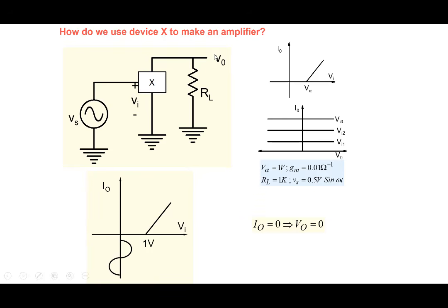So the issue before us is that we don't have an ideal transistor. We said an ideal transistor is not available. What you will have are elements with all kinds of non-idealities. So suppose we have a non-ideality like this here. Then if we simply connect an input to this kind of a non-ideal transistor, it's not going to amplify. Note that in this case it is 0.5 volt, and we may be talking about signals which are even weaker, maybe 1 millivolt here. So it would be very close to the origin here, and therefore the current is 0 and the amplifier will not work.